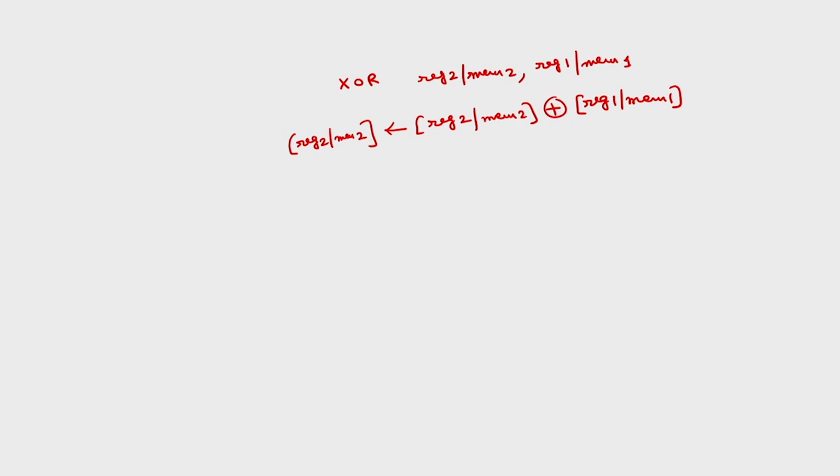So, these are the 5 logical instructions: 1's complement, 2's complement, OR operation, AND operation, exclusive OR operation. There are some rotate instructions. The next group is rotate instructions. We can rotate the contents of any register or any memory location either to the right or left. We know that in digital, if I shift these contents towards the right by 1 bit position, it becomes division. If I shift the contents towards left by 1 bit position, that becomes multiplication. This is the beauty of this shift operation.